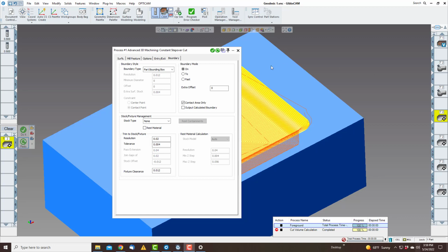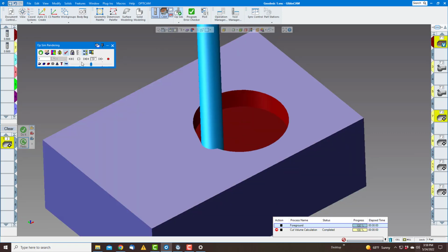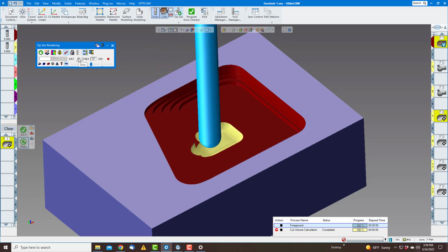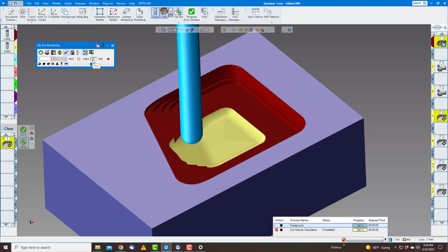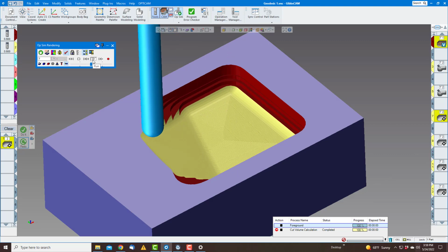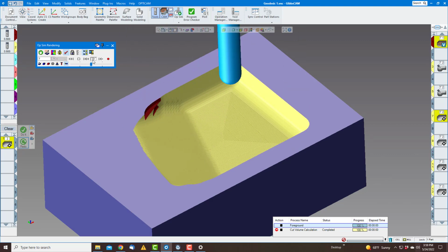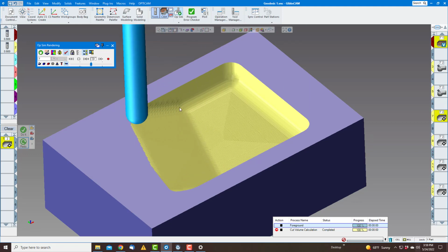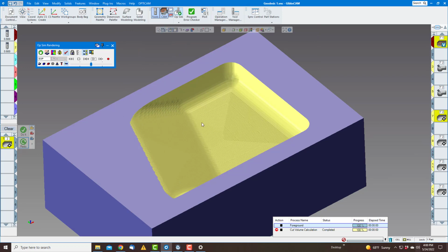Now we have our toolpath. So let's run that. So we'll just do the volume mill and this toolpath. So the volume mill first. Then we'll come back and we're doing the inside to the outside. So what's nice about this versus, say, lace cutting, which will leave larger steps 90 degrees from the toolpath, this way it goes clear around the part.